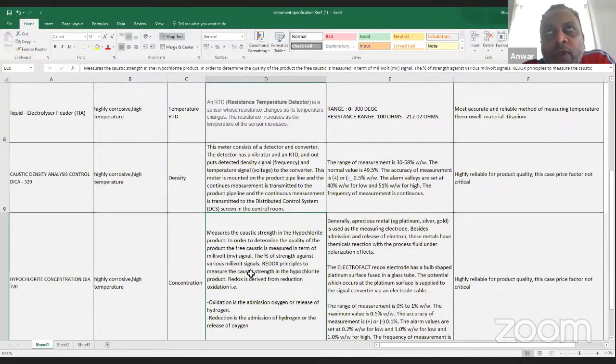So what we do with this excess chlorine, we send it to be absorbed in the absorption column. It's a packed absorption column. You have a chlorine stream coming from the bottom, and a shower of 20% caustic soda from the top of the column.